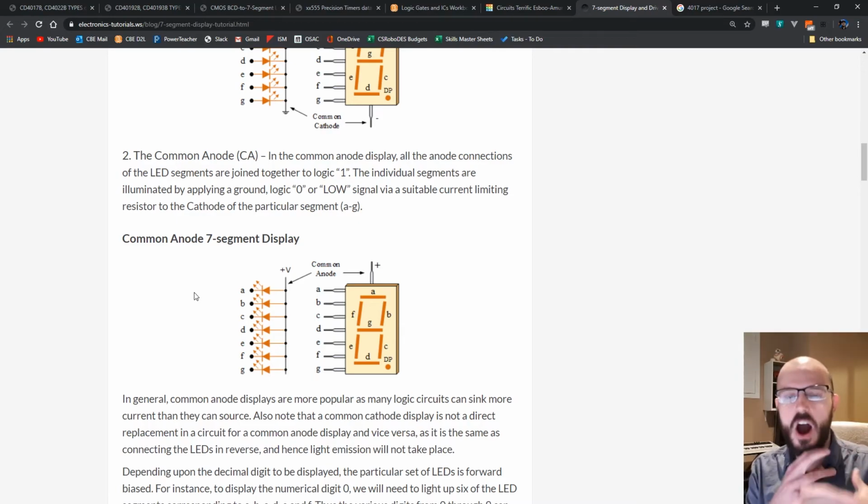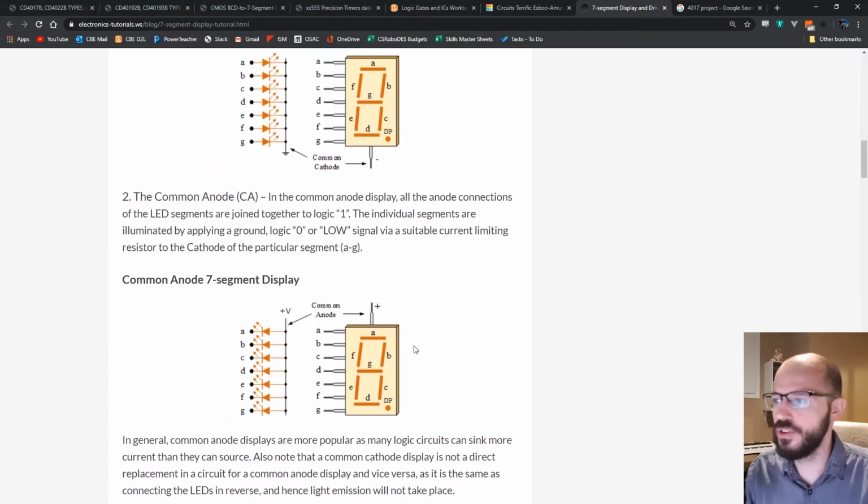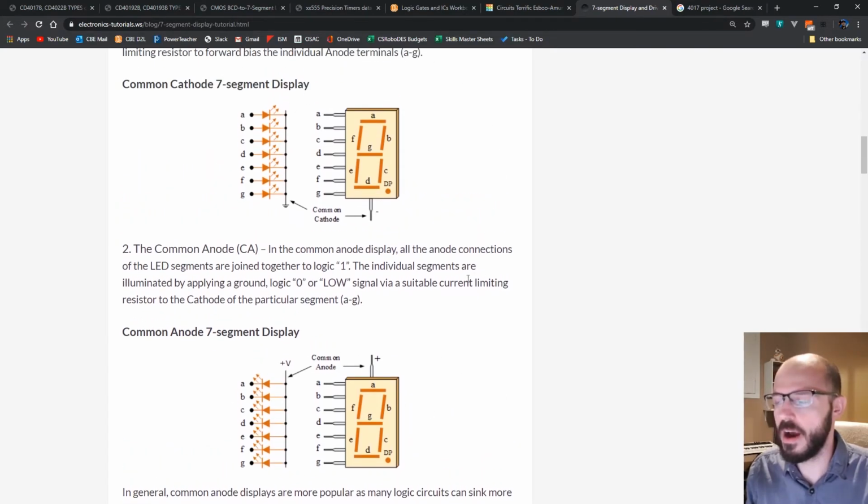So it needs the opposite kind of behavior, all of those signals on, unless that specific LED is supposed to be on, in which case that signal has to go off to turn the LED on. Confusing, backwards, is what it is, okay? It's just 2 flavors that these 7 segments come in. I didn't do my due diligence and check what came in your kits from Freenove, so that is my bad.